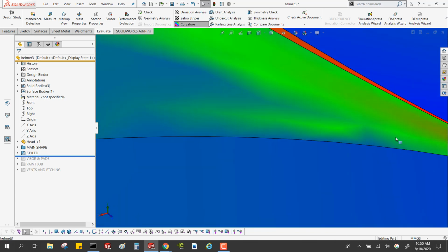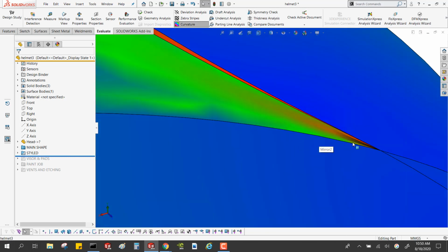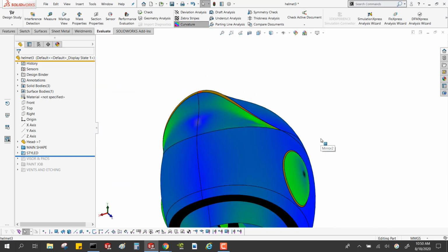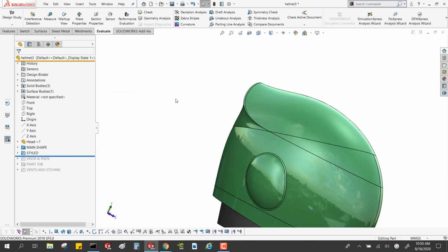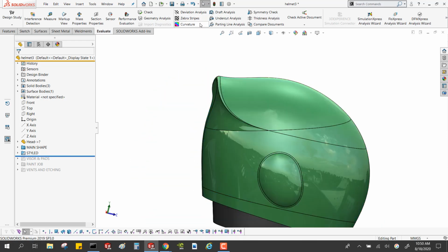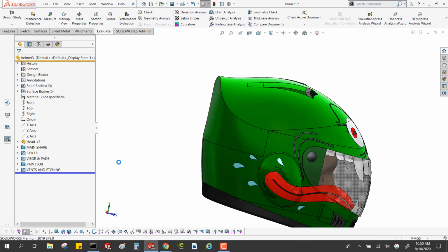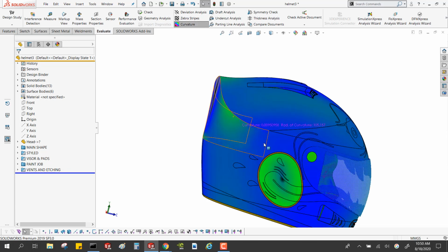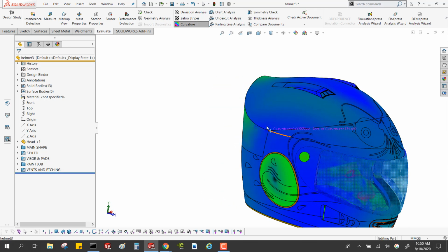Again, once you start to see ripples like this, also spikes in curves and things like that, that curvature command can help you target areas that you might need to work on. And again, a lot of surfacing is doing patchwork. At some point, I cut away that geometry and added a new one so that we wouldn't have that horrible curvature in there.